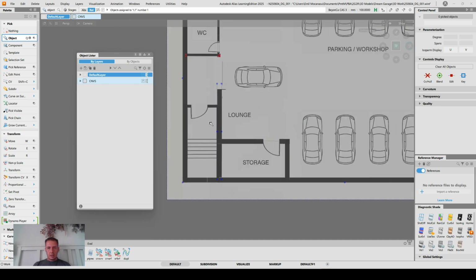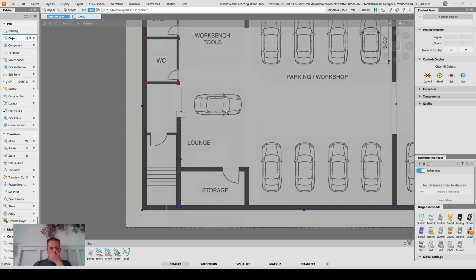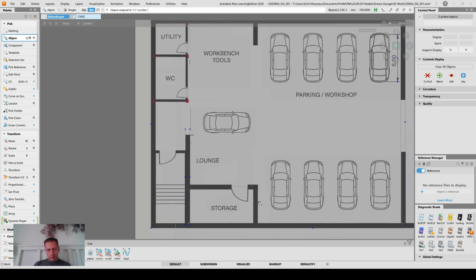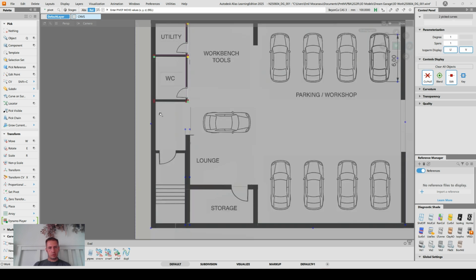Cool. Now, let's make this storage room, and I've reconsidered that segment, the blueprint there, and I want to make this out of drywall. So I'll take these two curves and these two, copy paste them, and take the originating curves and just move them wherever I need them.